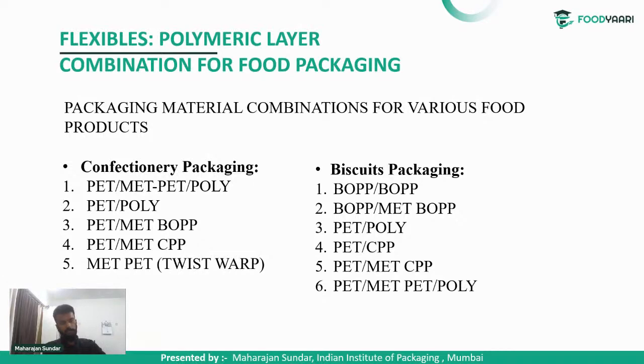Once a product is packed and printed, it cannot be left open. For the product to regain its original state, as manufactured, till it reaches the end user, it should be properly sealed. Mostly the inner layer of a packaging material will be a sealing agent, and it should give heat seal stability. The seal should withstand for a long time until someone tries to open it.